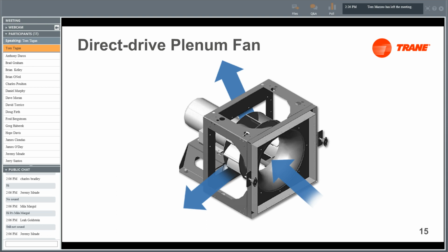The way these fans operate is usually through the use of a variable frequency drive that allows the fan to operate at different RPM, thus changing the airflow and the static pressure characteristics. And there are fewer moving parts, so you don't have any belt-related drive losses. There are less inlet and outlet obstructions. They're typically more efficient, quieter, and experience less vibration than your forward curved or your housed fan.